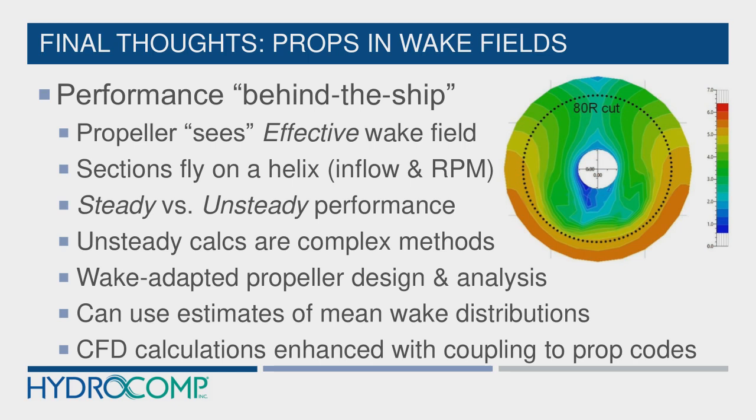Now, when we talk about hints or design practices for where to place the inflow plane, or where to capture the inflow velocities, typically it's a plane, a disk that's upstream of the propeller just a little bit.